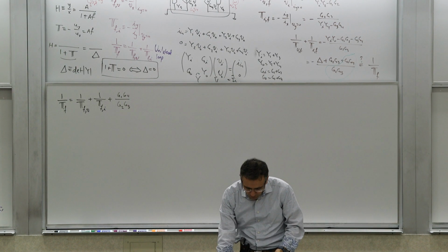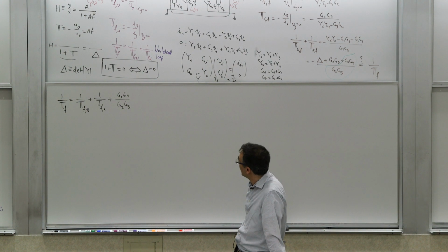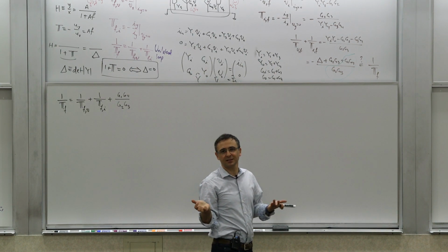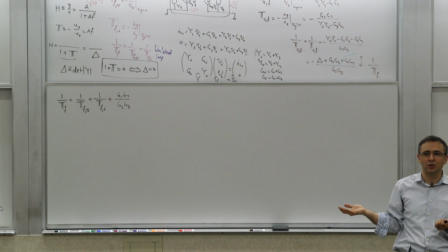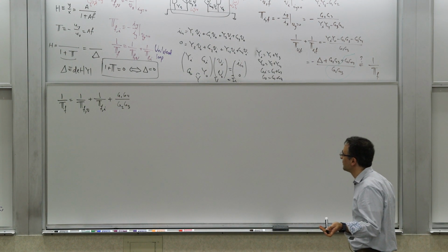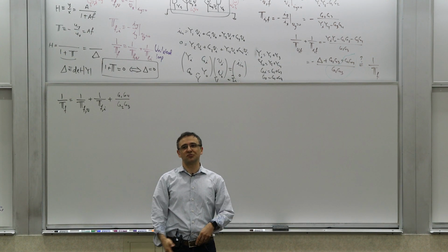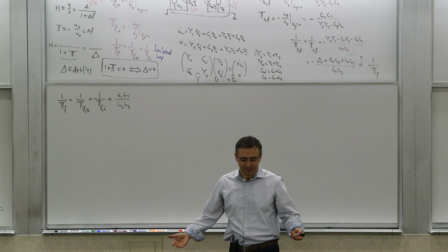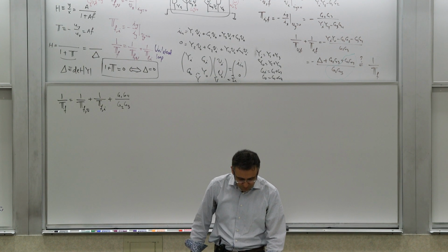But the question is, what is this quantity? Because this is useless. I mean, it's fine, but it's useless for analysis and especially for design. Those things we know how to calculate, but this thing we don't know how to calculate. What do you do in a circuit? G1, G2, G3, G4 is like some abstract. Unless you want to fall back on two-port analysis, which is really not the way to do circuit analysis in feedback analysis. You can analyze, but you can't design based on it. You can do whatever you want with it, but it's not useful. So what do we do?